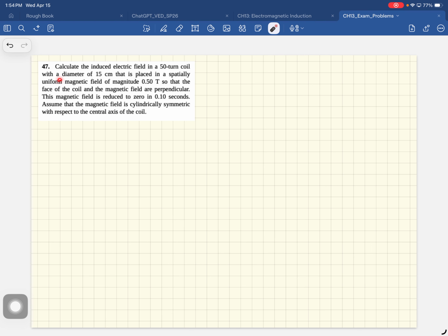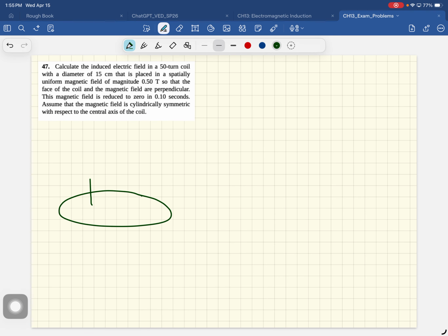Okay, so here's a long solenoid, and let's say it's wound like that, and the current is flowing like so. If the current is flowing like that, then it produces a magnetic field inside the solenoid. So it's a cylinder with wires wound around it, and this magnetic field is inside the cylinder. And the magnetic field strength is given by B equals mu naught, n is the number of turns of wire per unit length, times the current, okay?